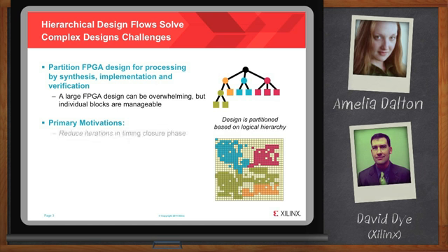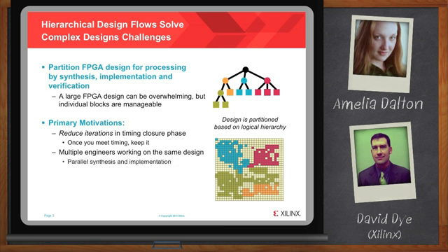So what you want to do is meet your goals for these smaller pieces and then lock down those results. And by doing so, designers can significantly reduce the number of iterations through place and route. Even when you're making changes to some modules, preserved modules are not going to change, so you're not chasing down moving targets.